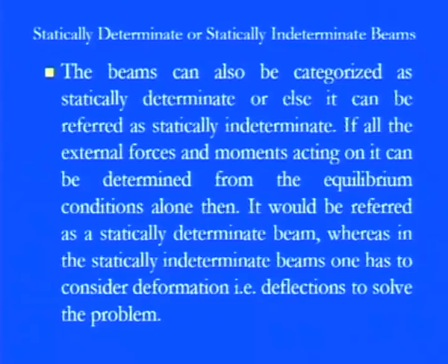So how these bending stresses are set up along this particular beam, and if you are saying that they are well balanced, that means the counterbalances of these stresses are there, and accordingly this balance theory applies, and that's why we say that these beams are statically determinate beams. Whereas in statically indeterminate beams one has to consider the deformation or deflection to solve the problem.